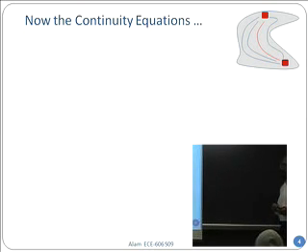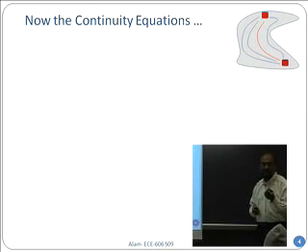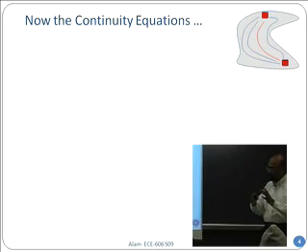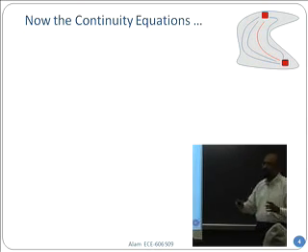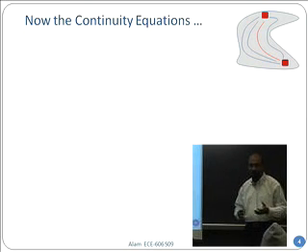Now assume that I have divided this region into many minuscule squares, or in 3 dimensions many minuscule cubes of size A. This size is not, of course, atomic size. I'm talking about more like 15 to 30 angstrom, a relatively big region, almost macroscopic in terms of properties. Effective mass is valid, mobility is valid, those concepts are valid, but it is small compared to the device dimension.